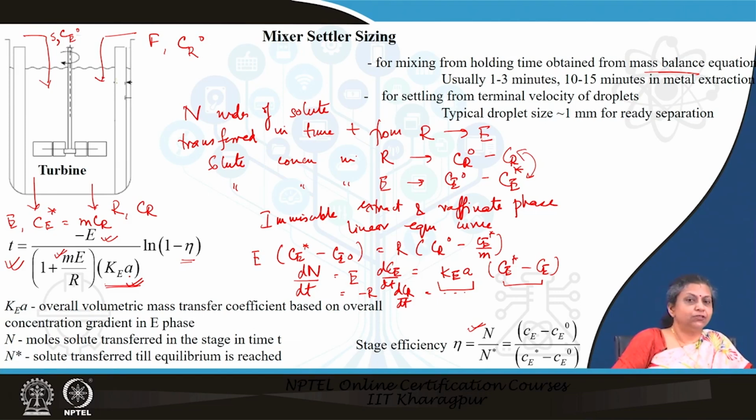And again, we have to remember that whatever solvent you take and whatever feed you take, there will be some amount of contaminant, some amount of surface active agent, something will be there. With every such contamination, the mass transfer coefficient is going to change drastically. So, normally we do not have data on this, and just like I mentioned in adsorption, in this case also it is the same.